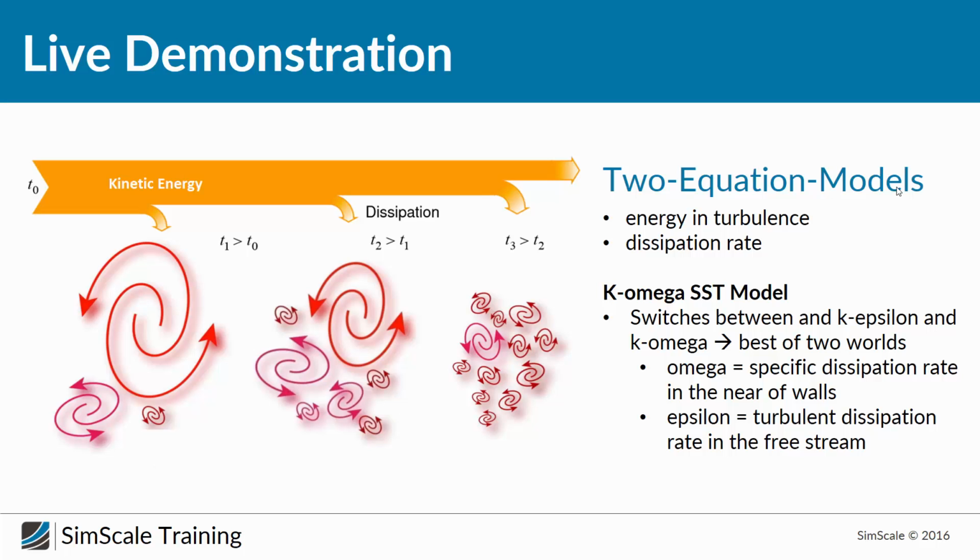It's just a help for us. One of them is the turbulent kinetic energy, and the other is the dissipation rate. And right now what we're doing is adding these two transport properties to our existing ones. So instead of only pressure, velocity, temperature, we also have the turbulent kinetic energy and dissipation rate, and that helps us then to calculate turbulence in an easier way.